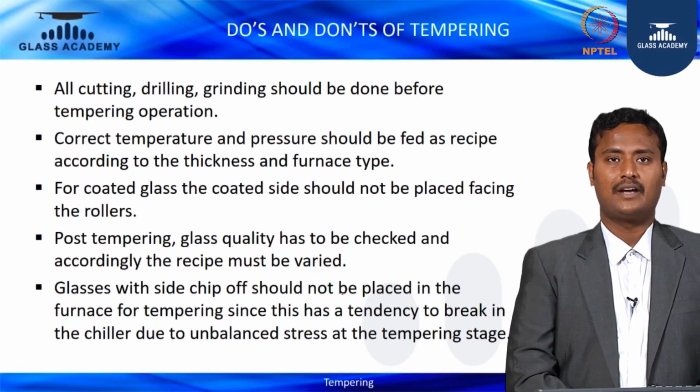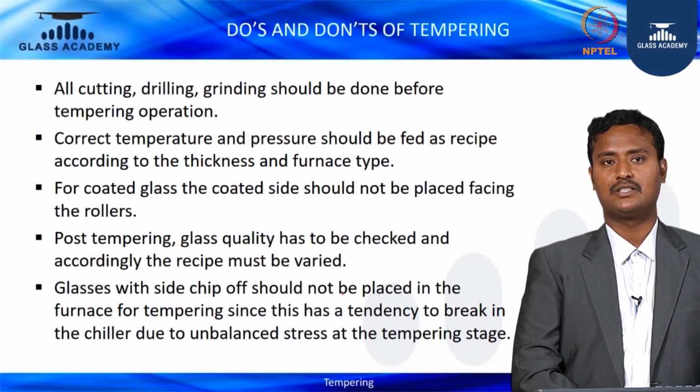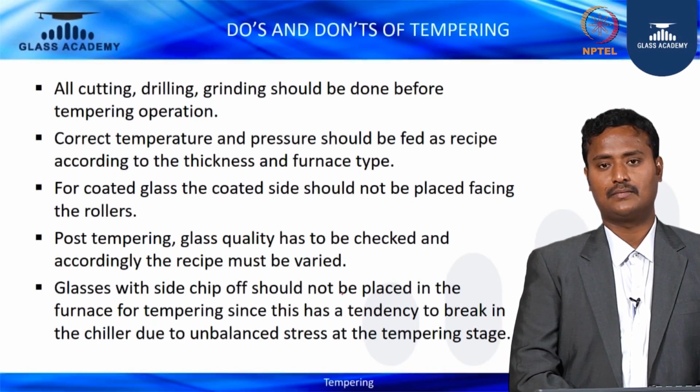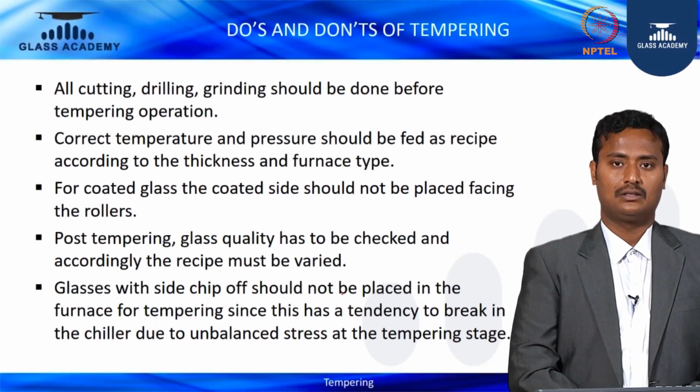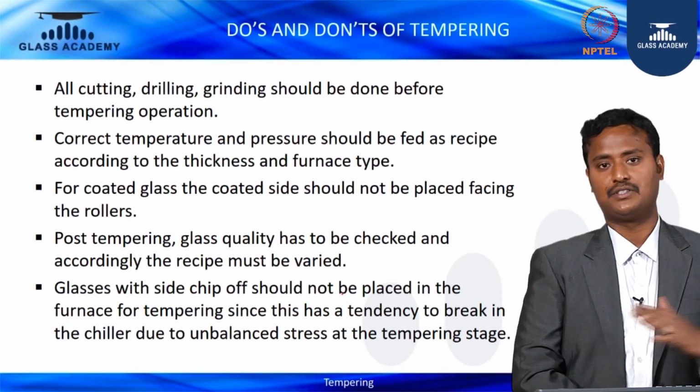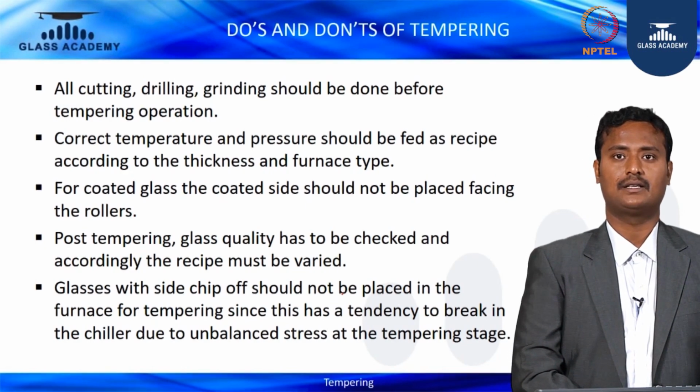Glass with chipped sides should not be placed in the furnace. If you keep the chipped glass, it will break in the chiller during the chilling operation, which is the quenching operation. The glass would break, so that's the one.